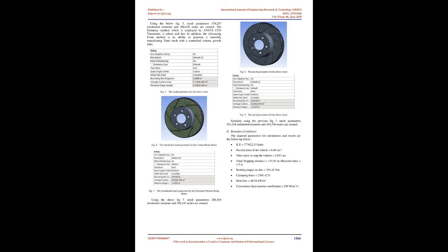brake rotors. A larger rotor moves faster through the pads, thereby generating more friction, which indirectly provides better stopping power. More surface area provides more for heat dissipation, letting disc and pads run colder. Thickness of the rotor determines the maximum temperature it attains during braking and is important when it comes to keeping the brake components well in the operating temperature range. In the considered scenario, to avoid changes in the braking torque, the effective radius and the thickness of all the models considered is kept the same.